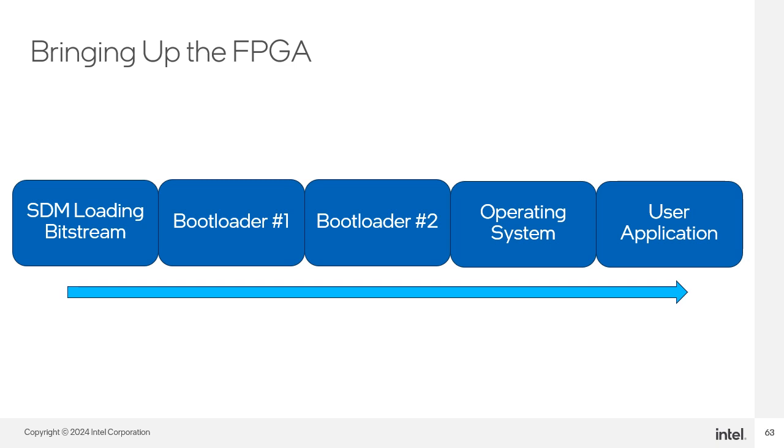The first stage bootloader is the first boot stage for the HPS. In FPGA configuration first mode, the SDM extracts and loads the FSBL into the on-chip RAM of the HPS. The SDM releases the HPS from reset after the FPGA has entered user mode. After the HPS exits reset, it uses the FSBL hardware handoff file to set up the clocks, HPS dedicated IOs and peripherals. You can create the FSBL from one of the following sources.